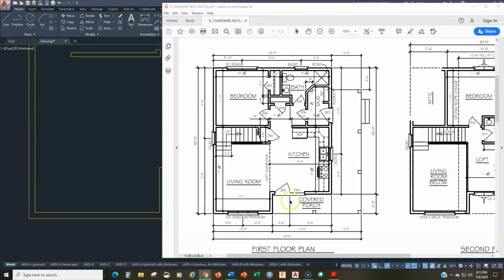So what that means in our drawing is that we basically have 2 3-foot doors, a 3-foot door here and a 3-foot door here for our opening, except the 3-foot door on the right is going to be fixed. So essentially we need a 6-foot opening. Okay. Now, we're not going to be able to center that, right? Because you see the opening, the front door is biased closer to the side. So we get to kind of choose how much that's going to come off of that.